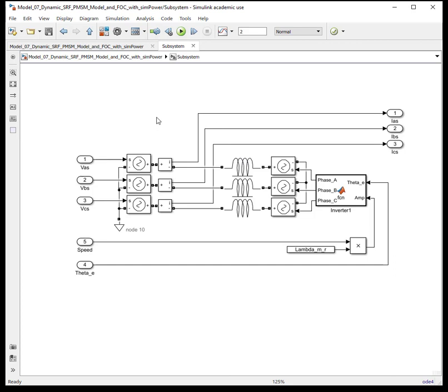Another important fact I want to mention here is this neutral point. Adding this neutral helps solve these equations. Sometimes I've seen the model throw out an error because it's having trouble finding a 0 location. So I would throw in this neutral point either here, or you can throw it in here. It doesn't make a big difference.